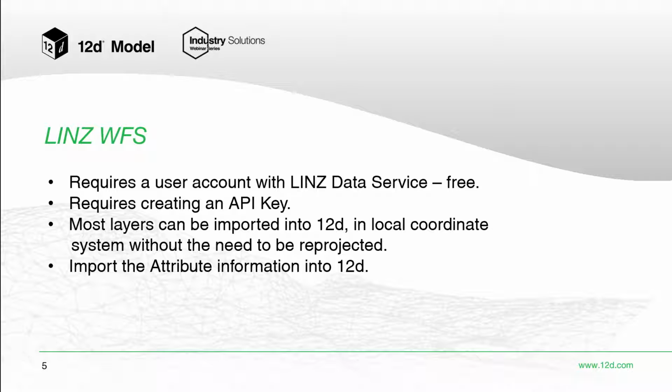This import will not replace the Land Online XML extract, because on the LINZ data service, even though they have the vectors, they don't have attributes for every single underlying vector. So if you're doing any cadastral work, you will still need to use the Land Online export to bring that into 12D for your tracing.